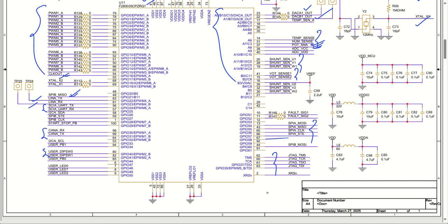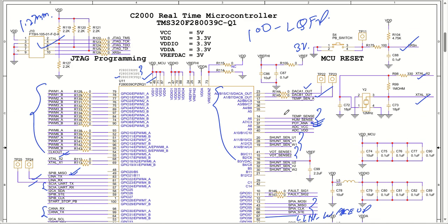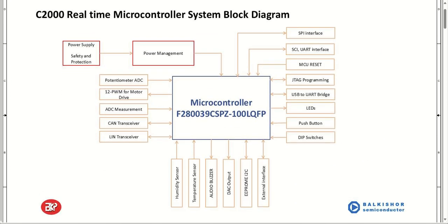One thing you can add is this part: let us say one of the GPIOs, you can name it and put it LIN wake up. Okay, WAKE up. So LIN wake up control can be done by one of the GPIO pins, because we have LIN TX, LIN RX, and the wake up signal was also required. So this was all about this particular microcontroller system that we had talked about. So all the block diagram and different peripheral connections of this particular microcontroller that we have seen.